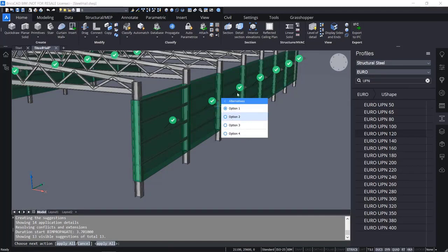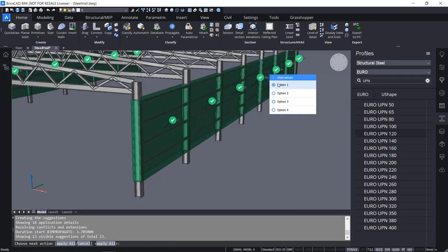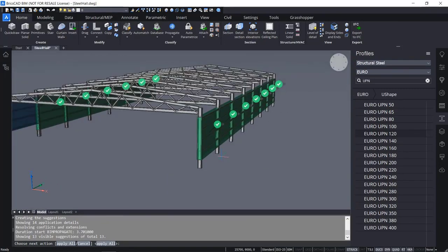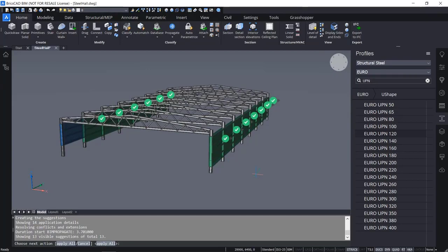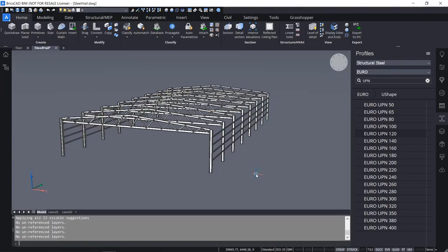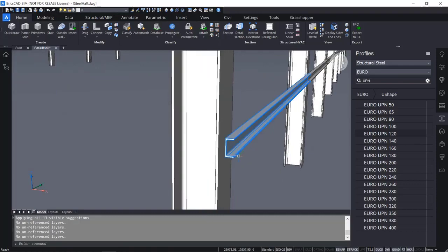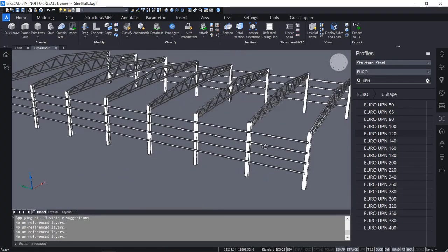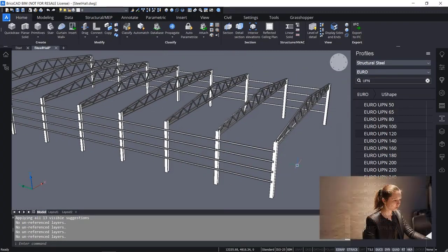And I want to do that for every one of the check marks, so that you always have the option of the sidebars at the outer location of your structure, and then press enter to accept. And then you will see that in fact they are at the outer location. So that's good. We now modeled some sidebars where you could now model further cladding onto etc.